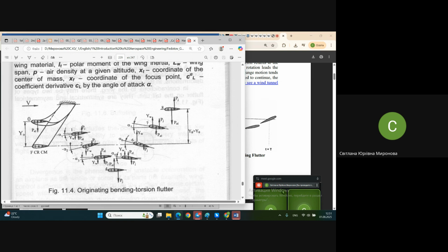They counteract this attempt of the relative wind to rotate the wing, and it starts retwisting again, and they are trying to place the wing in the previous position, and the cross section rotates down again, but it rotates too much because of these balances of forces, and now it's in negative angle of attack. But here we still have the velocity of relative wind, and this relative wind is trying to rotate the wing again. So it's like a superposition, a combination,